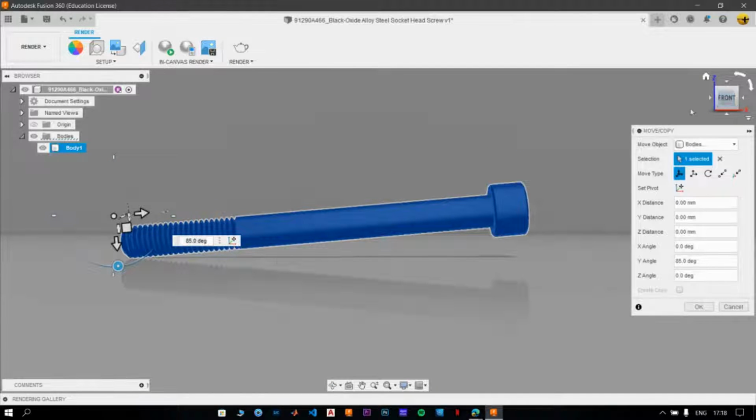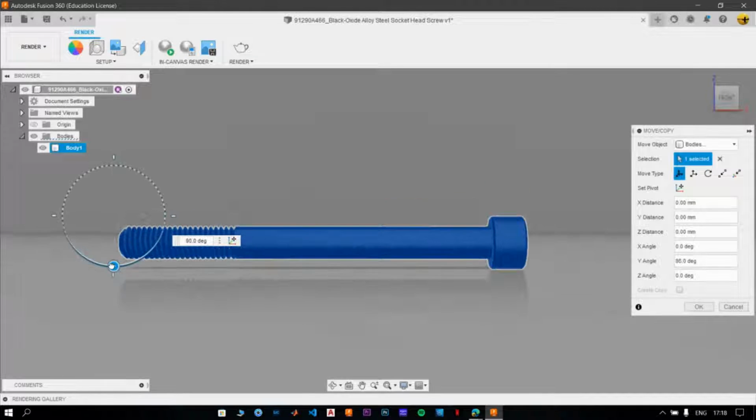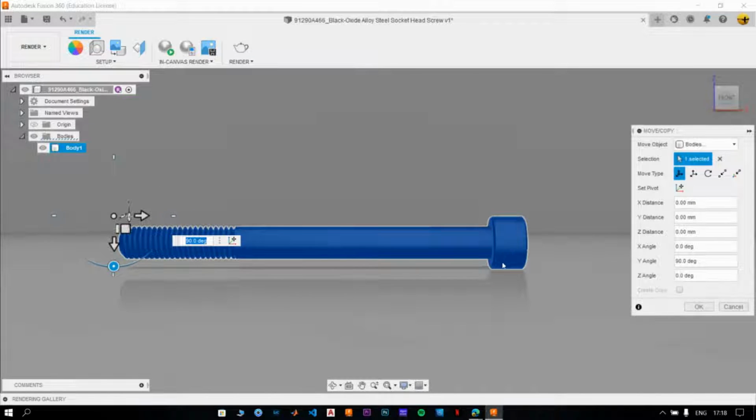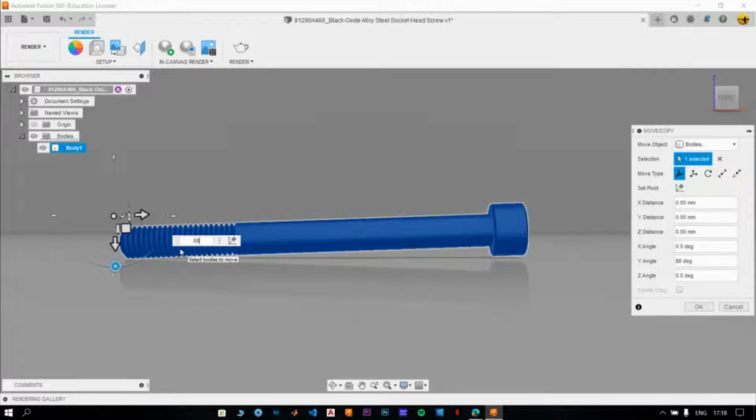Now, if you go to the front view, you'll be able to see that you need to give it some angle, because if you give it 90 degrees, it is not going to look good, because it cannot stay up on its head like this while the other half of the body is floating in the air. So you have to experiment with the angles. Maybe 88 degrees would work, or 88.2 degrees. So I guess 88.2 degrees, or let's try 88.3 degrees.